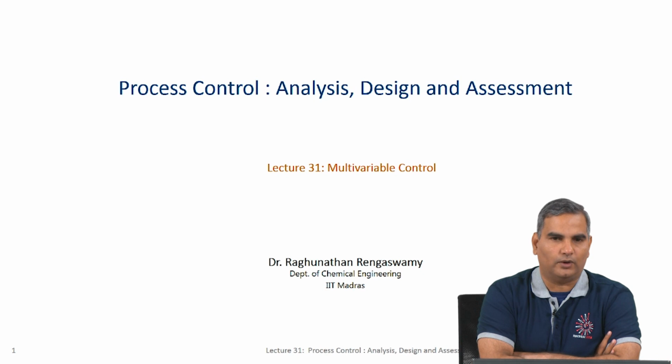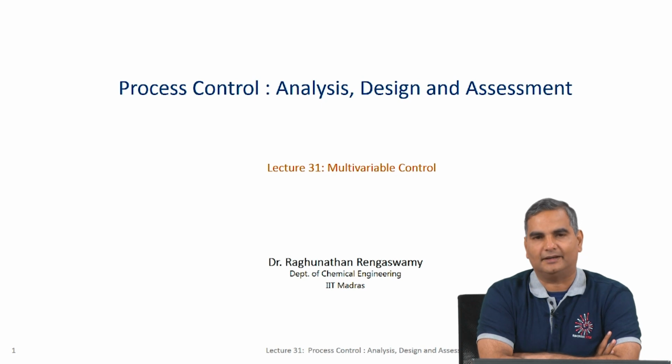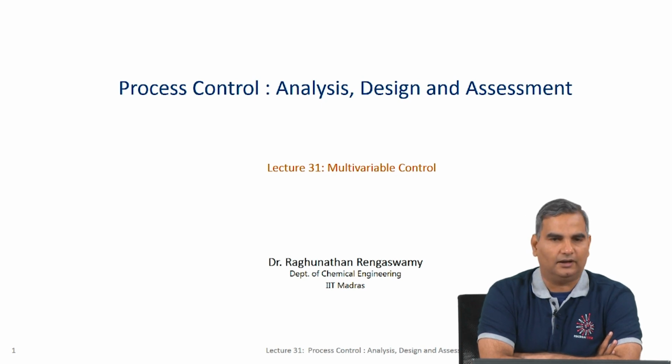So, that is the reason why we call this dynamic decoupling, whereas relative gain array is the first step in some sense before you actually do all the controller design, because you have to do the pairing if you are going to come up with, let us say 15, 20, 100 single input single output loops that you are going to design and implement.